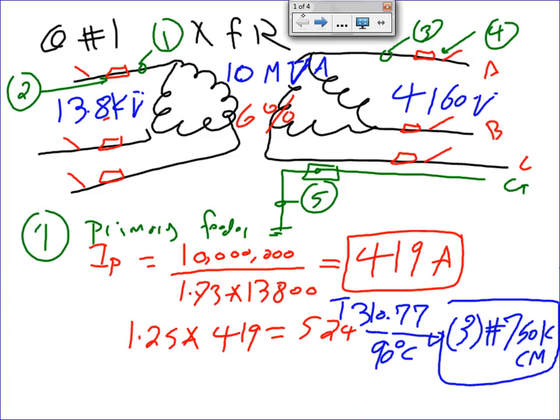But ground faults are very common. You're working on phase A and accidentally touch the frame here, which is grounded. That's a ground fault, very common. You're changing the ballast and you touch the frame or the conduit. So this will handle the first ground fault in any phase, no problem. Continuity of the system continues.